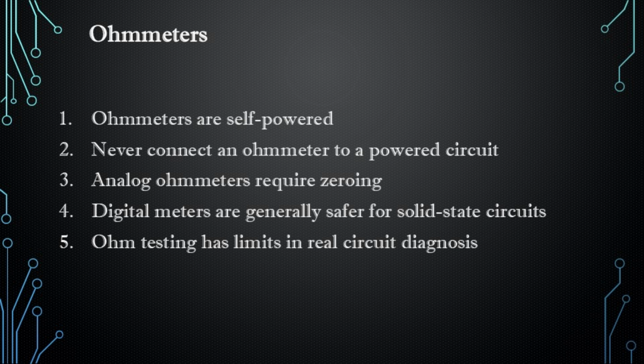But that does not mean ohm testing is always the best diagnostic method. A component or cable may pass an ohm check with the tiny current provided by the meter and still fail badly when the circuit is actually loaded. That is where many students need the next step in their thinking, because the low current test is not always telling the whole story.